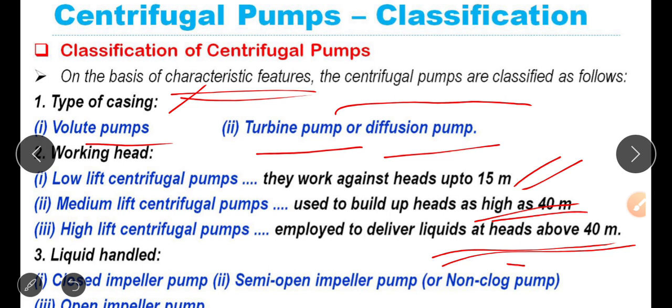Based on liquid handled, there are closed impeller pump, semi-open impeller pump or non-clog pump, and open impeller pump. Closed, semi-open and open: these are the three types.